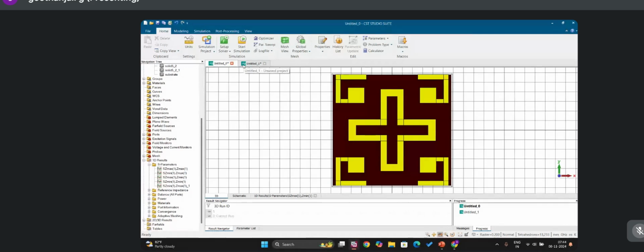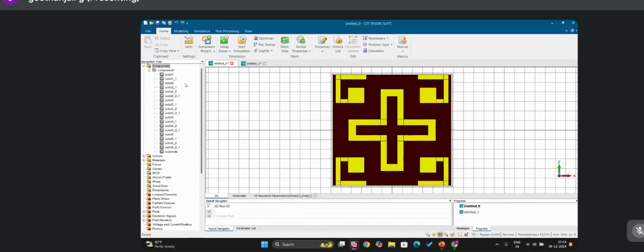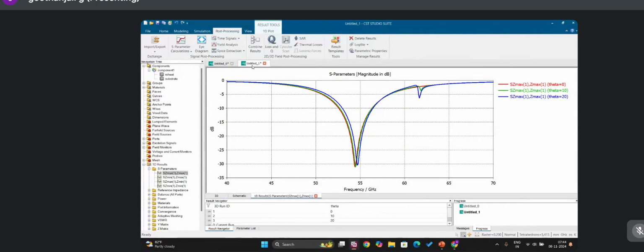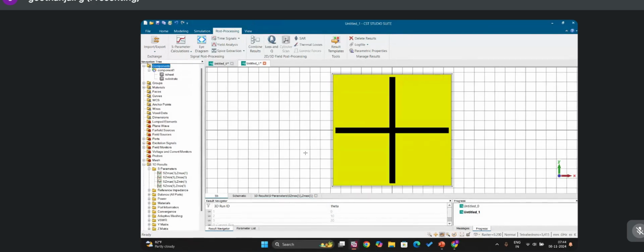As for now, I will explain. We have designed the band stop FSS by using the loop resonator, as Sir said. This loop resonator is used to achieve the band stop characteristics. We have designed a miniaturized size of FSS for very high frequency that covers the radar frequencies, and for band pass we have used polyimide substrate.